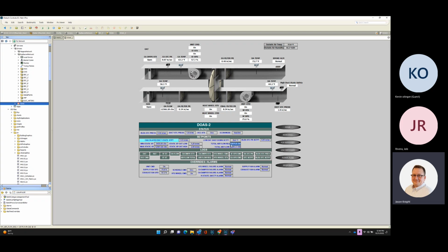So here's what they're asking for, 12,079. And here's what we're actually delivering, 12,065. And you'll see it fluctuate a little bit here. It'll catch up. That's pretty darn accurate. It's pretty close. So remember, your duct static pressure resets based on the min and max requirement from the total of all the boxes. And then over here is just a quick snapshot of what the boxes are asking for and what the DOAS is actually delivering. Does that make sense?